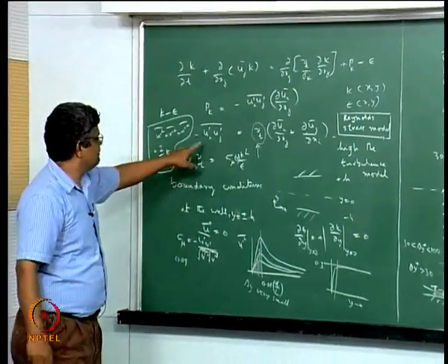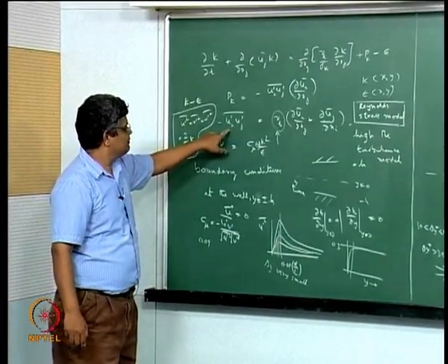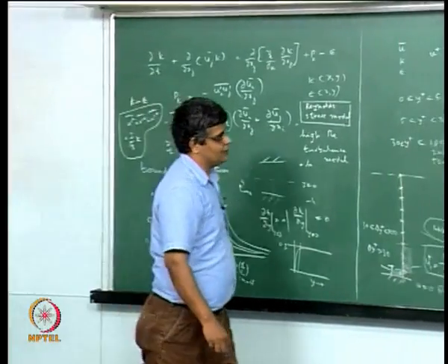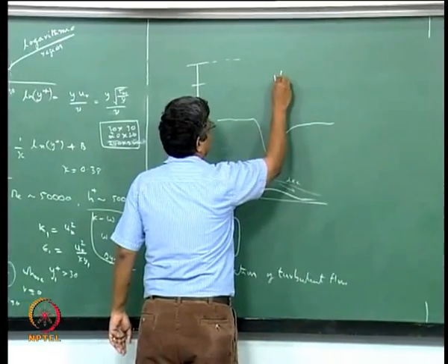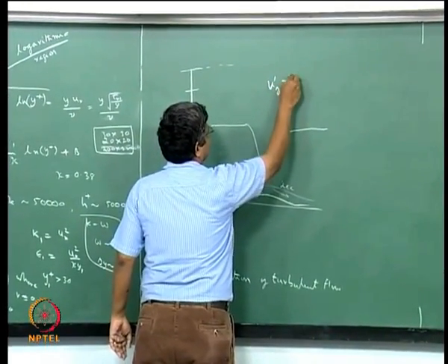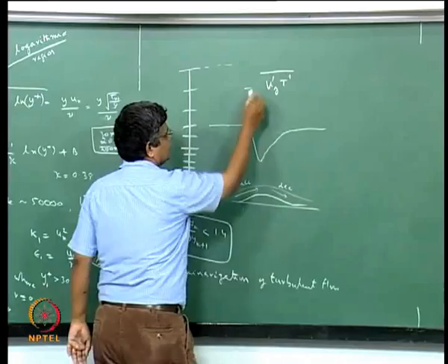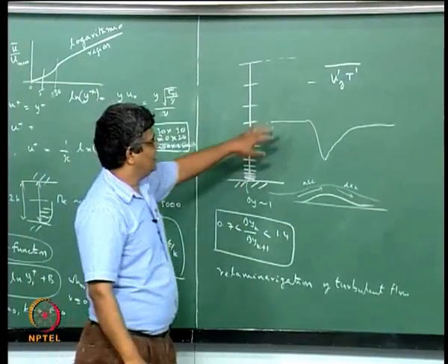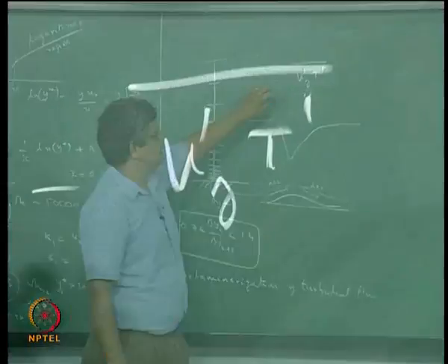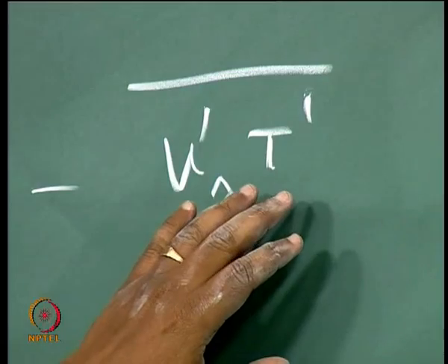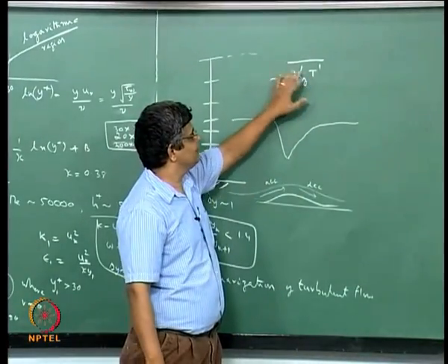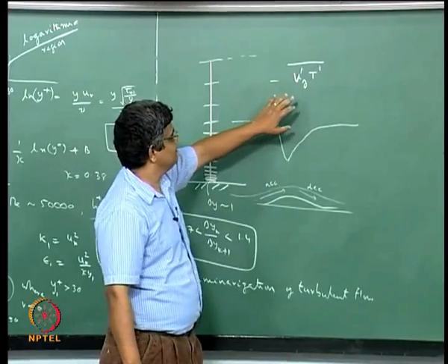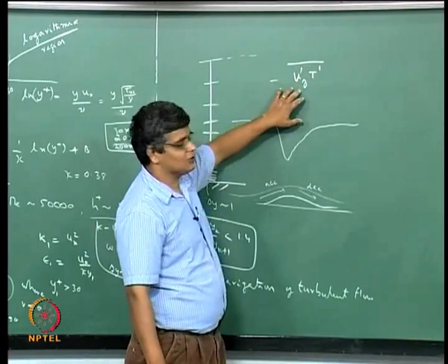So we can come up with a time averaged energy equation which looks very similar, and in such a case, instead of having a term like ui prime uj prime, we will have a term like uj prime T prime as the equivalent fluctuating temperature flux, which times Cv will give us the energy flux associated with turbulence.